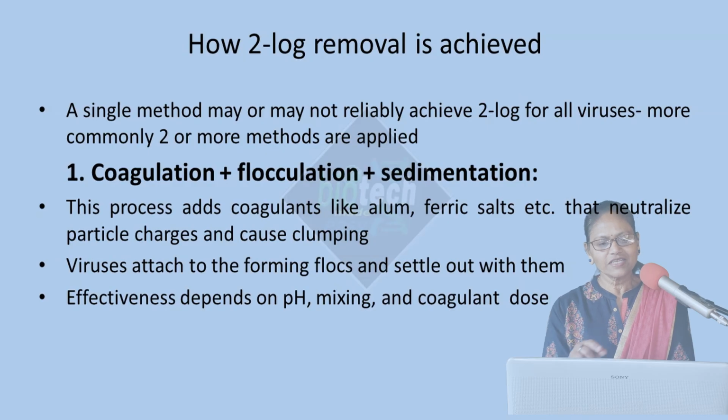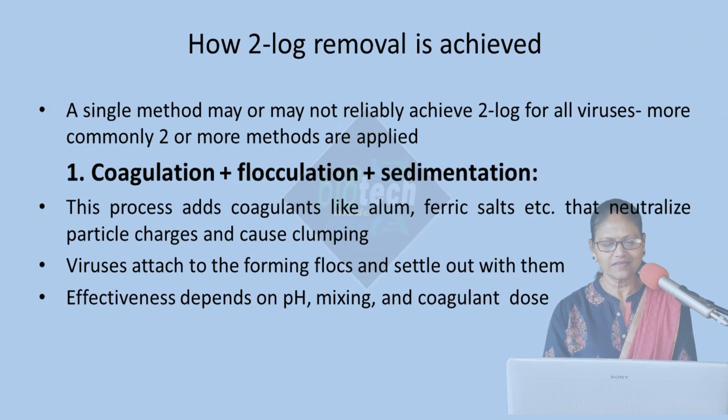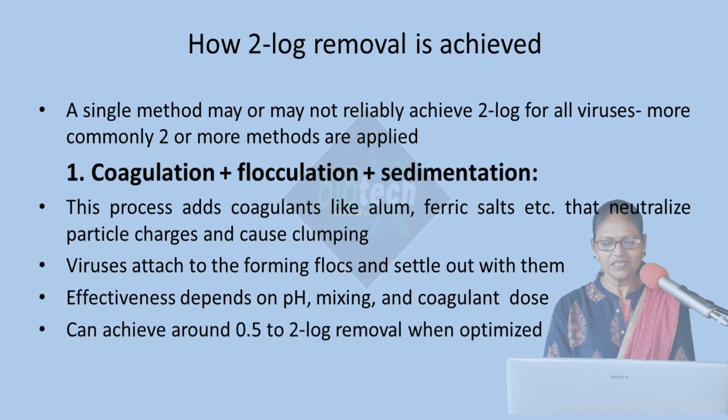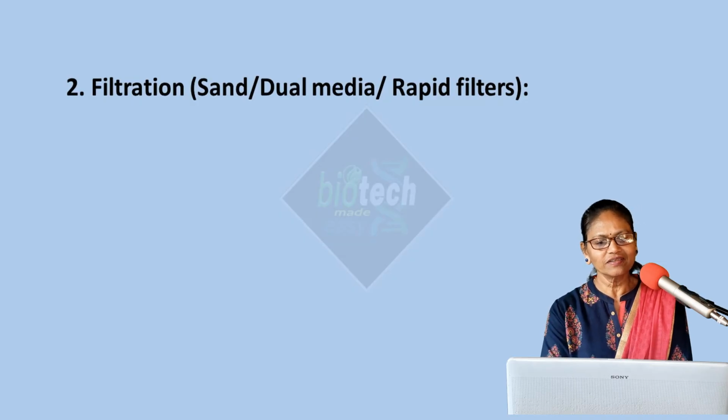The effectiveness of this method depends on the pH, mixing, and coagulant dose. So, all those factors are there. Around 0.5 to 2 log removal can be achieved when it is optimized. Then the second one is filtration.